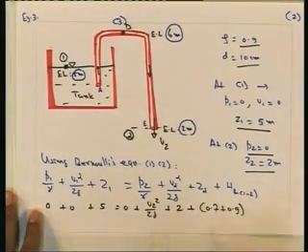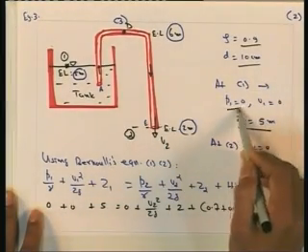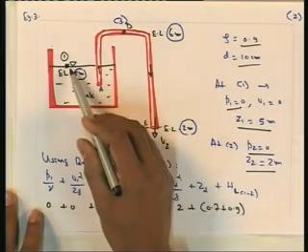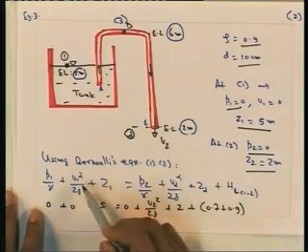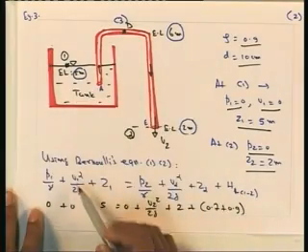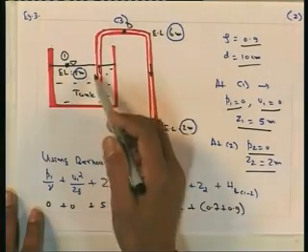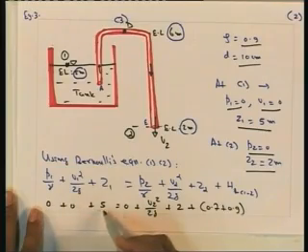So, this is the Bernoulli's equation. Here you can see that we have already seen P1, the pressure at point 1, is atmospheric, so we consider it 0. So P1 by gamma is 0, and the velocity at this location is also 0, so V1 square by 2g is 0, and Z1 is already given as 5 meter. So, 0 plus 5 is equal to